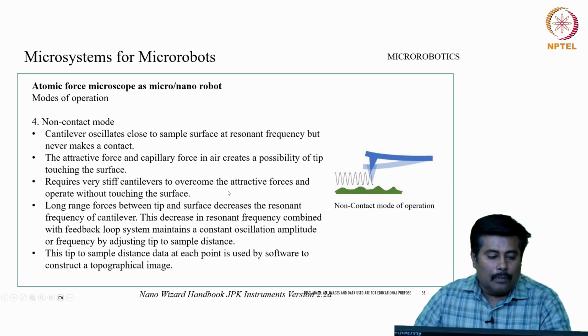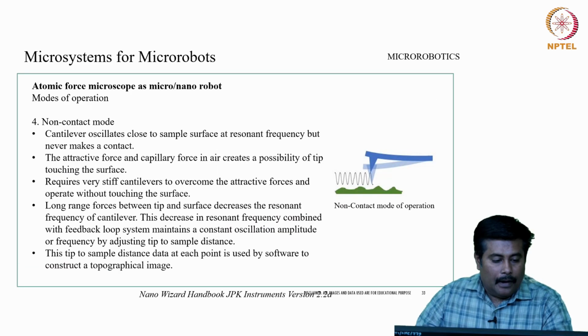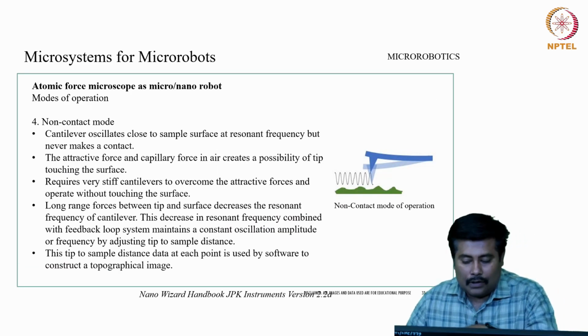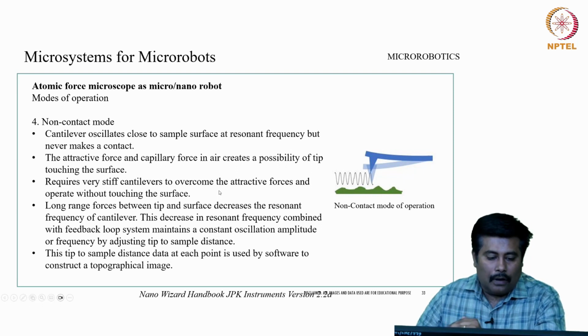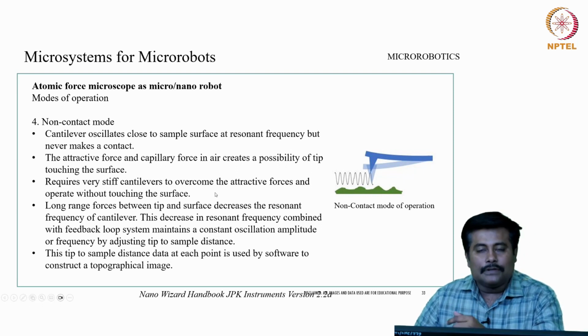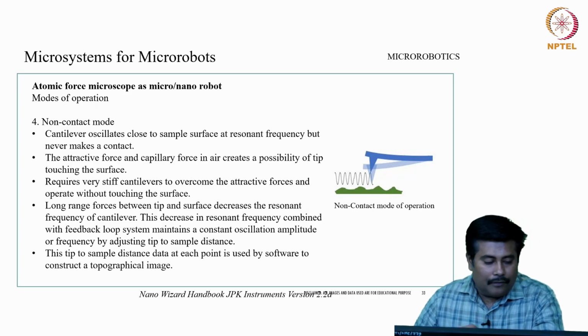Now, let us talk about the non-contact mode based system. In this non-contact mode, the cantilever is almost equivalent to a tapping mode, whereas in the non-contact mode the cantilever oscillates close to the sample surface at a resonance frequency, but never makes contact.